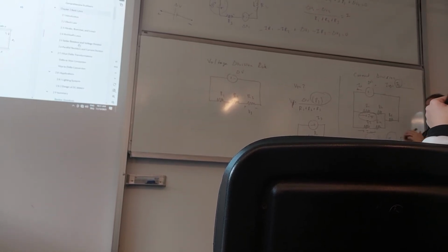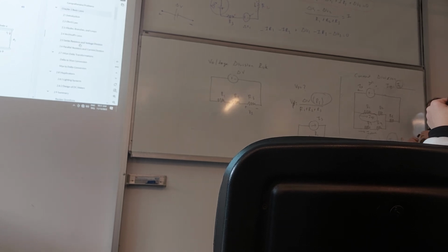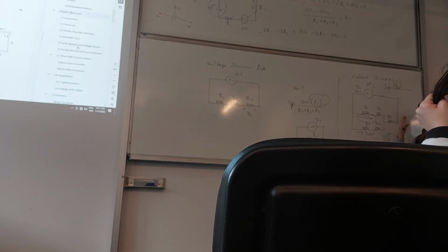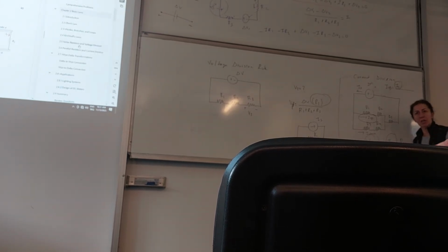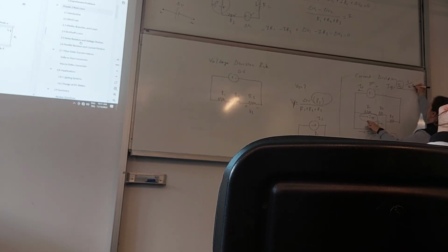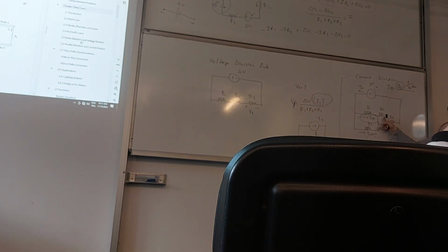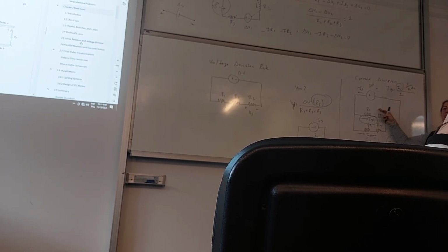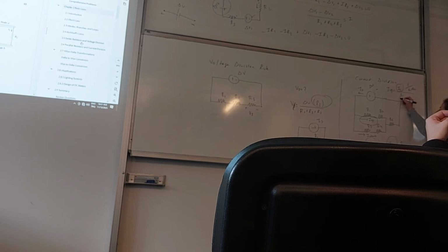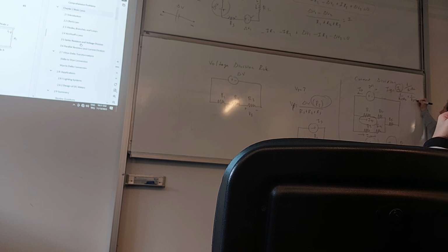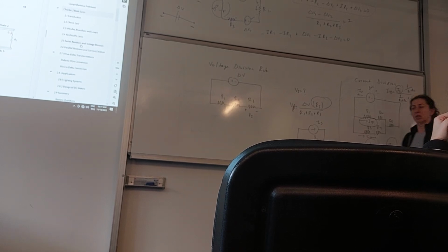Remember, this is the current in a parallel connection, so it's not linearly proportional to the resistance, it's inversely proportional to the resistance. Because if your resistance is higher, the current is going to be smaller. So this is 1 over R1 plus R2, because the current is not just flowing through R2. It is flowing through R1 plus R2. In here, this is going to be 1 over R equivalent of this system, right? Which is 1 over R1 plus R2 plus 1 over R3 plus R4.